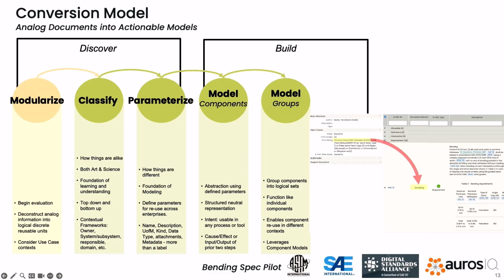And so now we get into grouping, which is where it starts to get, I think, kind of exciting. So you're really having to think about all these component models that have been built, and you might have some simple examples of higher level models, where it's 2 or 3 components stitched together through a higher level model. But you have to ask the question, does this model work on its own, or does it only work when it's evaluated together in a group of others? And that question sounds simple, but can actually be really deceptively complicated.